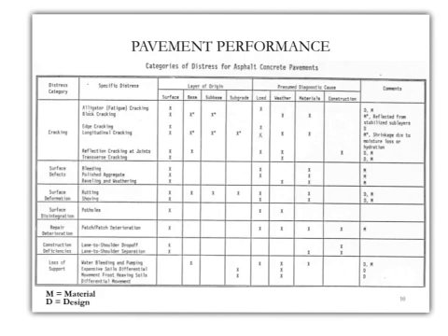Then once we specify exactly what type of distress and under what category, we move on to at what layer this crack starts. Does it start at the surface, or at the base, or at the sub-base, or even at the subgrade? So for example, block cracking: we can see block cracking originating at the surface, or at the base, or it can even be at the sub-base. Typically it doesn't really start at the subgrade.